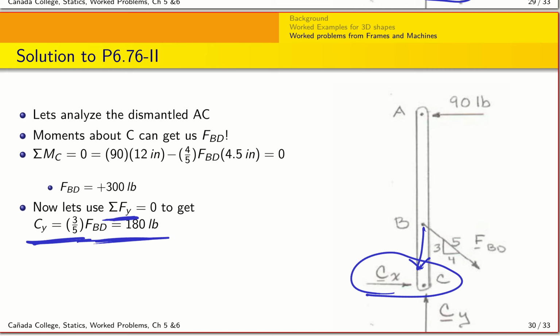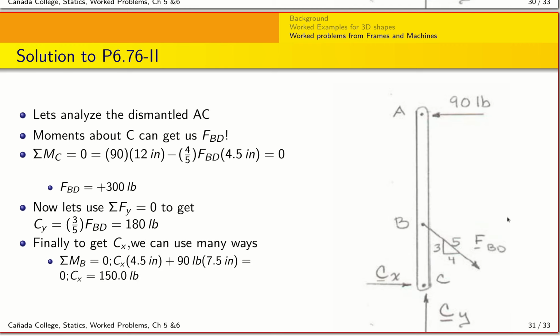So what do we need to do here? Well, you can see here that the force A and the force Cx are actually trying to rotate this member about B, right? So the way to get equilibrium is to take the moment about B, so that this object is in equilibrium, and when you do that, you can actually get to Cx. That's because now we have known quantities here, and the only missing quantity was Cx. So that's one way to do it.